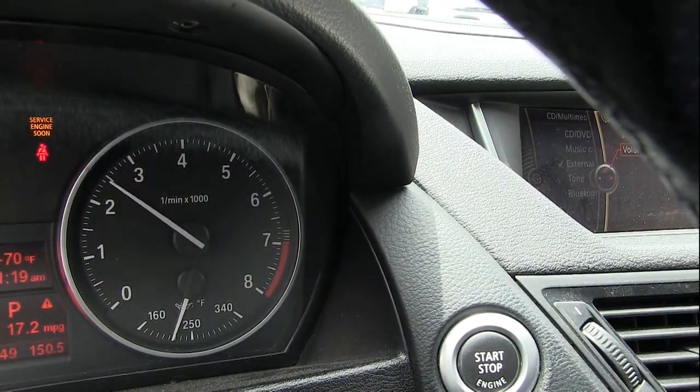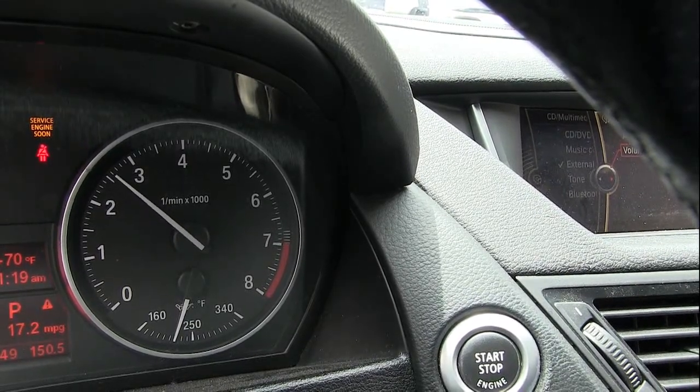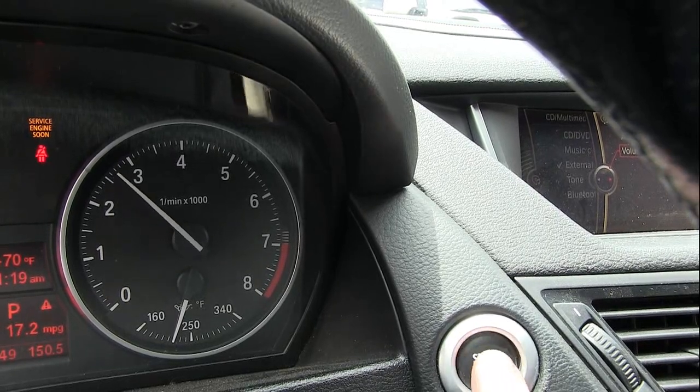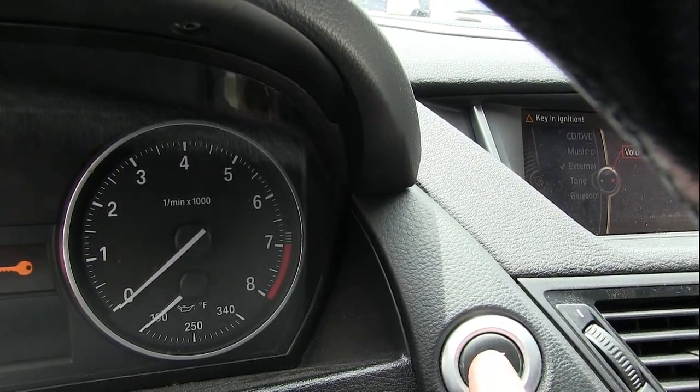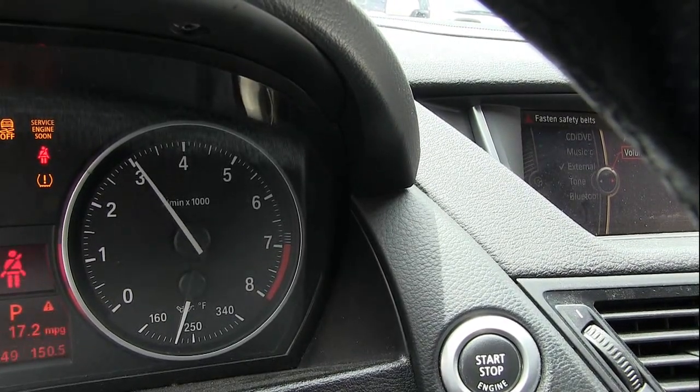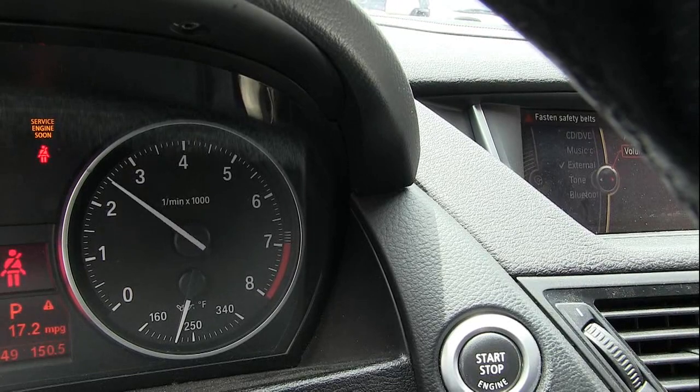If the engine starts to limit your throttle opening where you can't rev the car and you start to lose throttle control, go ahead and shut the engine off quickly with your foot on the brake and restart it, and go back and just start to clean it again. Now I have throttle control once again.